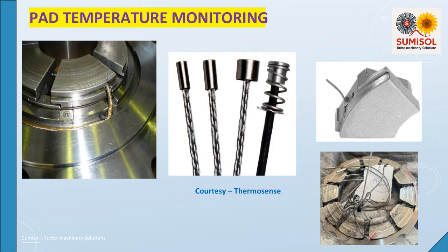Precautions are to be taken while fixing temperature sensors on pads to ensure that hanging cables do not get entangled between the thrust collar and thrust pad. There are spring-loaded sensors available, and these types should be preferred over embedding type sensors, which require high-temperature sealants.